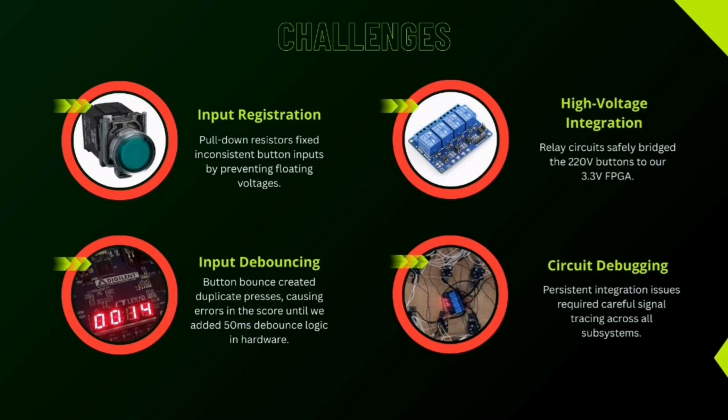Our fourth technical challenge was input registration. We discovered our push buttons weren't registering input consistently. The solution came through proper implementation of pull-down resistors, stabilizing the input signals and eliminating floating voltage issues.